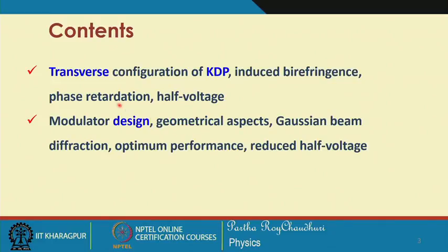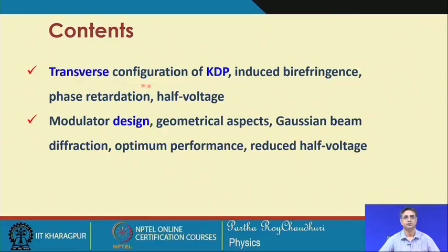So now we will continue this discussion with the transverse configuration. In this transverse configuration we will see how the induced birefringence and the consequent phase retardation can be used to switch the modulator, and what the requirement of this half-wave voltage will be in this case.